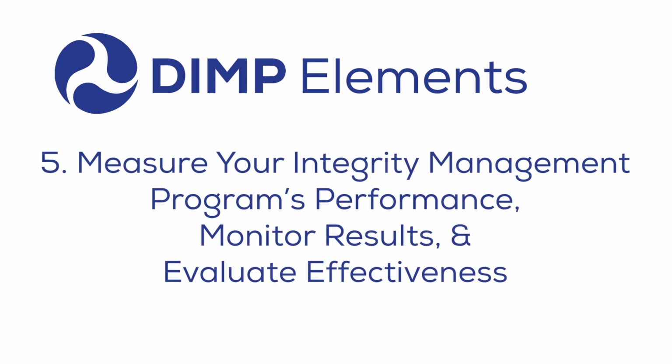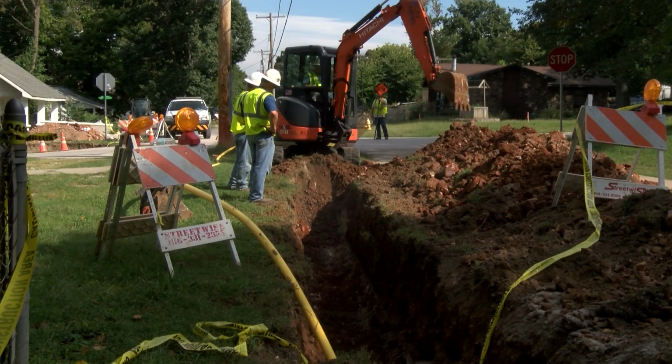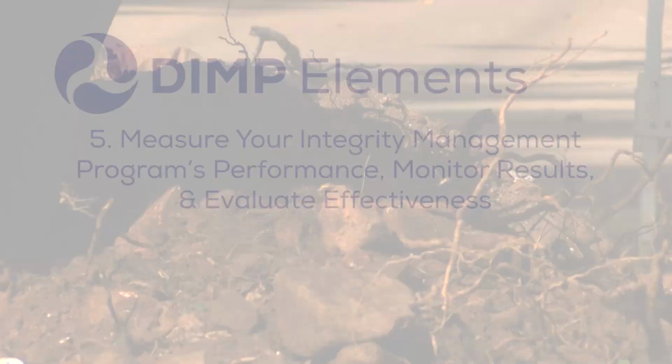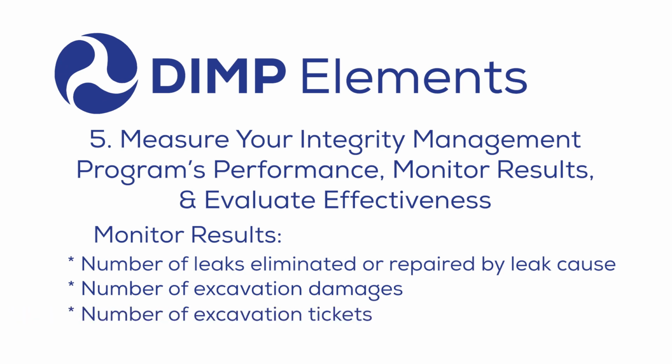Number 5, measure your integrity management program's performance, monitor results, and evaluate effectiveness. This starts with the identification of goals or performance measures for the measures you have selected. Operators must track their progress towards achieving these performance measures. PHMSA requires that operators consider the number of leaks eliminated or repaired by leak cause, and the number of excavation damages and excavation tickets. Operators are encouraged to identify and track other measures that are applicable to them, their system, and the risks to their system.